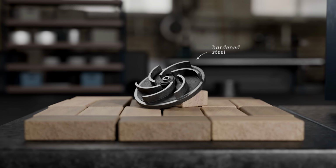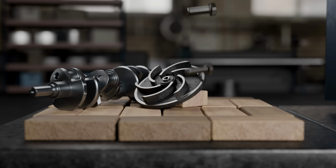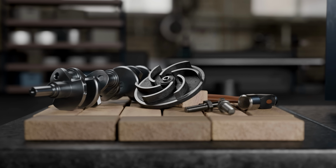Quenching and tempering is used for critical parts that need high strength combined with toughness, like crankshafts, high-strength bolts, tools, or heavy-duty structural components. It needs sufficient carbon to be effective, though. In low-carbon steels, even if martensite forms during quenching, there's too little carbon to significantly distort the lattice, so these heat treatments produce little to no increase in strength and hardness.